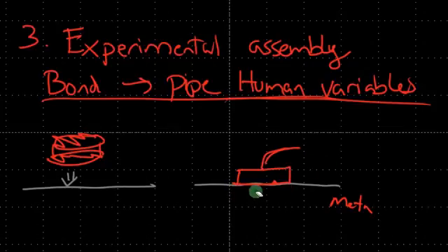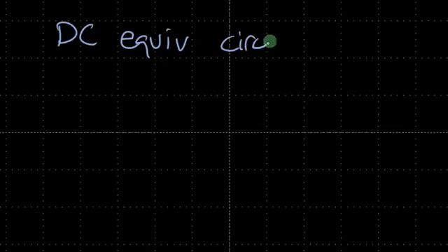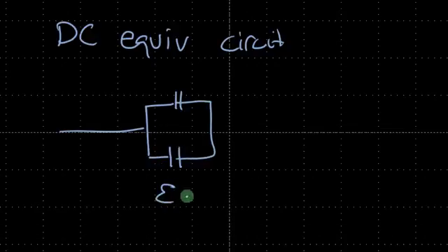So you have this contact, and when you vibrate the piezoelectric, it's going to be constrained, or semi-clamped. Obviously, it's not completely clamped because you can generate vibration. Semi-clamped. And what happens when you semi-clamp a material? Let me draw for you the DC equivalent circuit, and this also somewhat applies to AC too. Essentially, what happens to the capacitance? So this is the part related to the clamped.